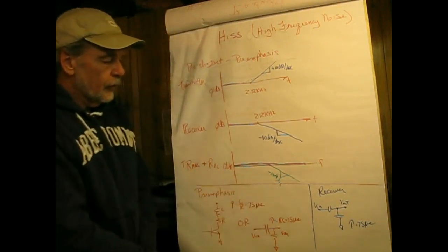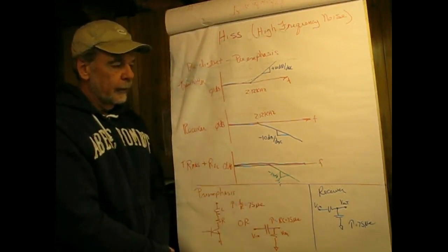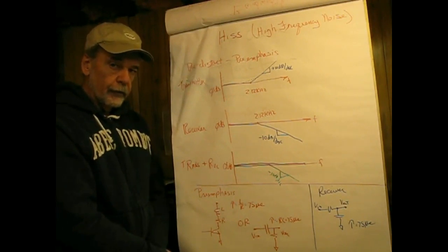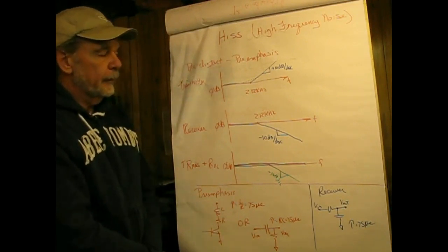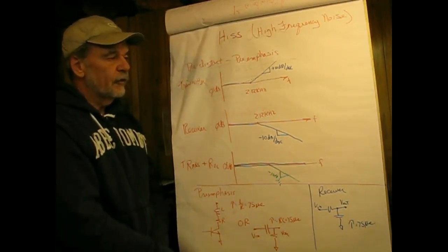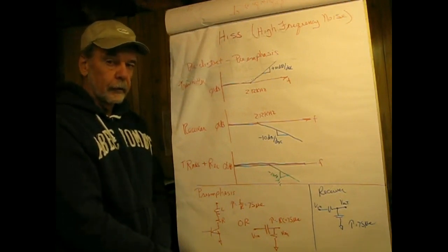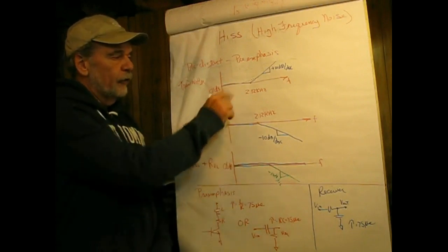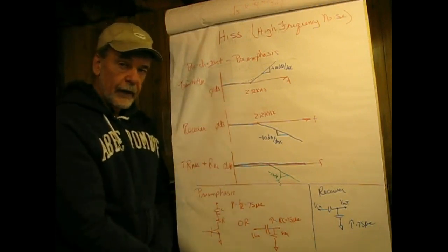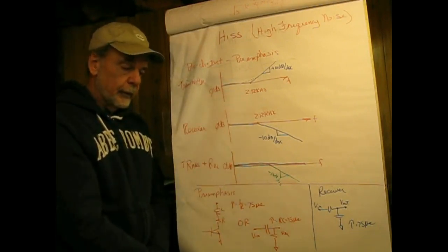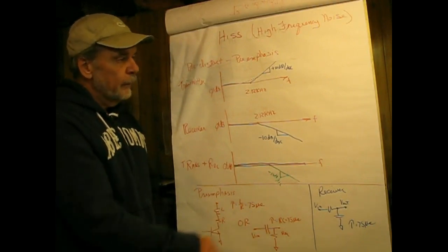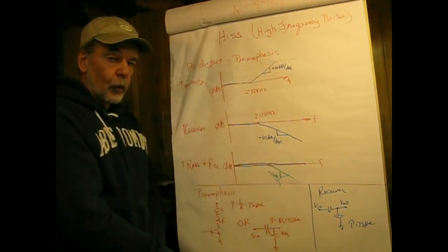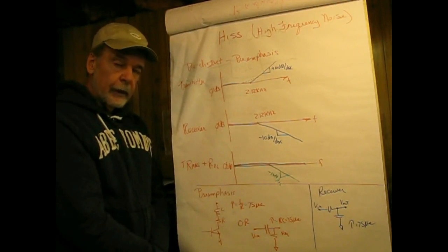So this idea of pre-distorting and then fixing it later is very, very effective. Now you might be thinking, well, what if I put on a 15 kilohertz signal that would, if we didn't have this, produce the same deviation as that of 1 kilohertz, which would be 75 kilohertz. Now that we've emphasized it, it would be way out of range, and that would be correct.